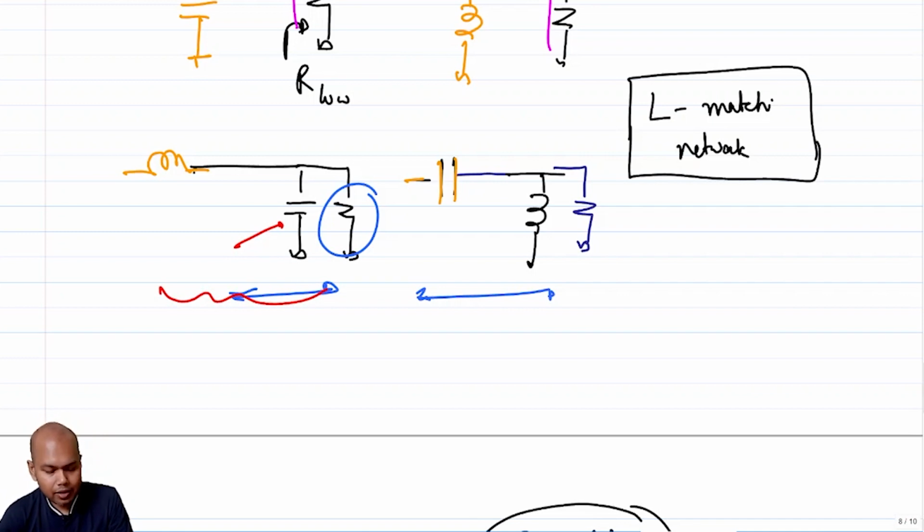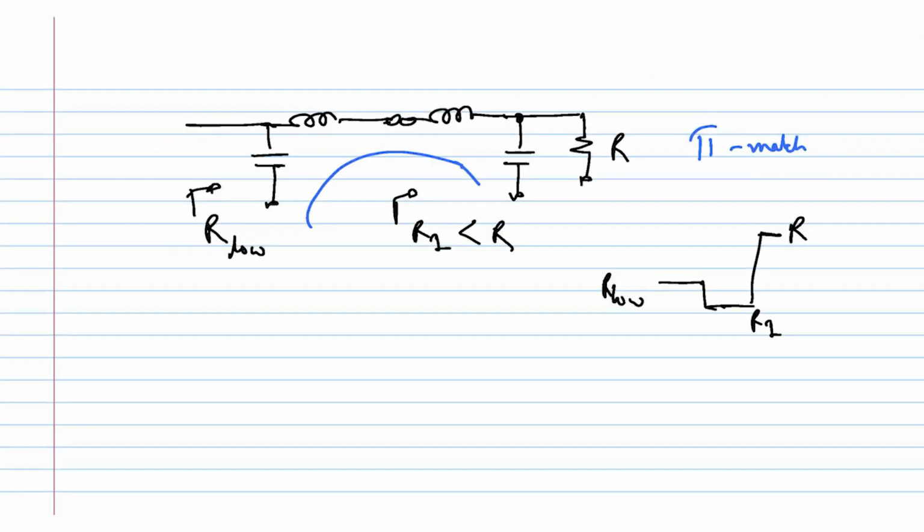So you will see that in many RF applications at less than 10 gigahertz or so, you will see networks which have one side being a grounded capacitor. If the terminal impedances of a matching network have grounded capacitances, those types of networks are often preferred, because if there is any parasitic capacitance associated with the following stage that it is driving, then it can be absorbed. So that's the only other thing that we should keep in mind, right?